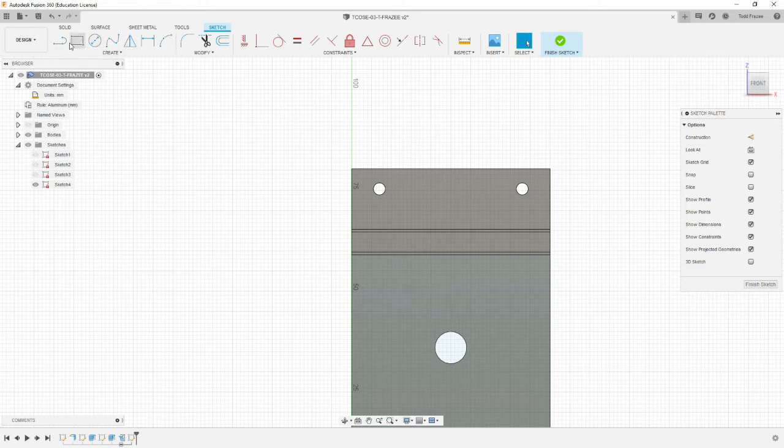So we're going to start with our line, and we're going to make it coincident with the edge, come up at an exaggerated angle, then try to go vertical, and then another angle to the right where it's going to touch the top. And I'll go a little bit past. And we're going to make sure that that end point is coincident with the top. Not perfect, but it's close.